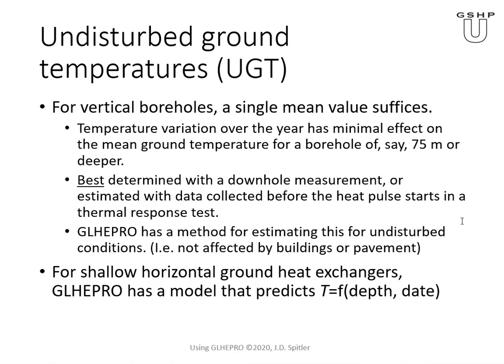All right, so it's true the temperature varies over the year in the ground. It varies a lot in the first meter or 3 feet. It varies, you can see a little bit down further to 15, 20 feet, but if you get much deeper, it's very hard to detect the difference over the year. So if you have a borehole, let's say 75 meters or 250 feet deep, what's happening in the top meter or top 2 meters probably has very little effect, especially since, at least here, the top of the borehole is typically down, say, 4 or 5 feet, so 1.5